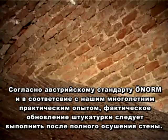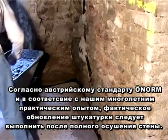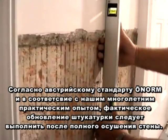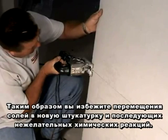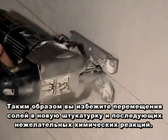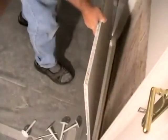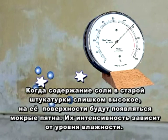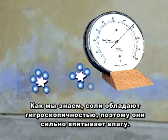According to the ÖNorm, Austrian standard, and according to our long years of practical experience, the actual plaster renovation should be performed only after the wall has been dried. One thus avoids migration of the salts into the new plaster and consequent undesirable chemical reaction. When the salt content of the old plaster is too high, moisture spots will appear on the surface. Their intensity depends on the level of humidity. As we know, salts have hygroscopic properties in that they strongly attract moisture.